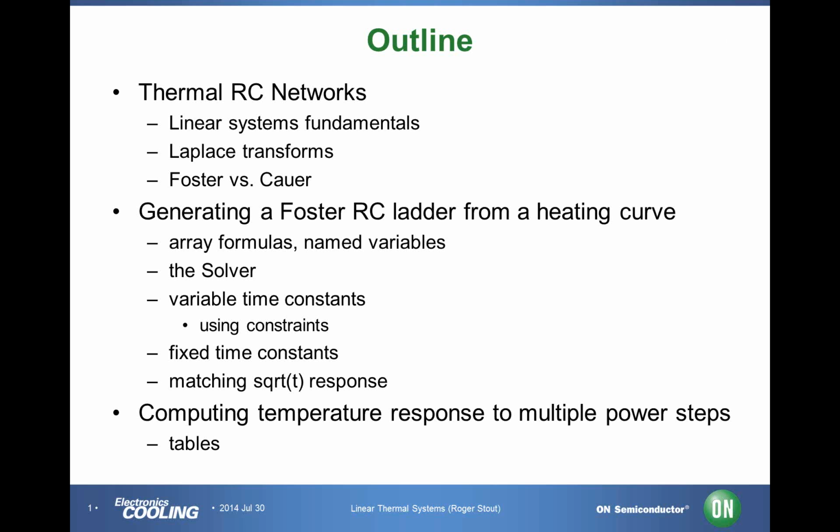In this case it would be an experimental curve that I got from test equipment in my lab. And in doing that, we'll get quite a few topics in Excel, things like array formulas, named variables, how to use the solver, using constraints on variables. In this particular case, whether we fix the time constants in the ladder or whether we let the solver find those.